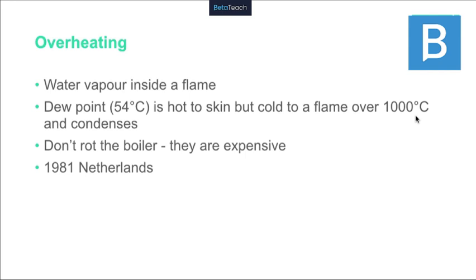If you increase the temperature of the water, you increase the rate of corrosion. So these single panel radiators that were in the 1960s homes, they were getting crudded up very quickly. A lot of people think it was all to do with the fact we had open vented systems. If you got your pump and your vent and your feed and expansion pipe wrong on them, you were pulling in air. And it was all about the neutral point and keeping most of the pipe work under positive pressure. But it's the temperature that was the real big driving force of the rate of corrosion.